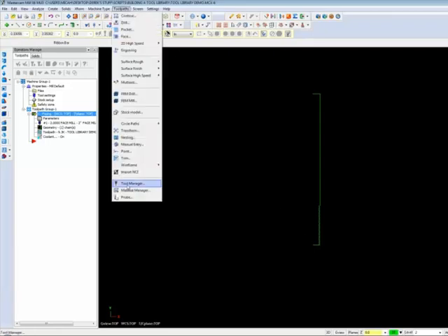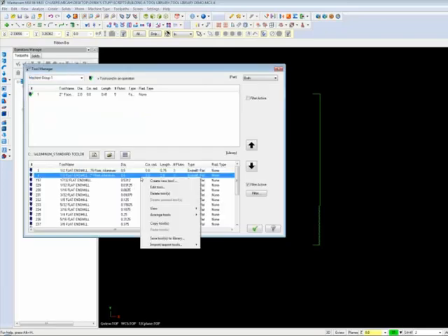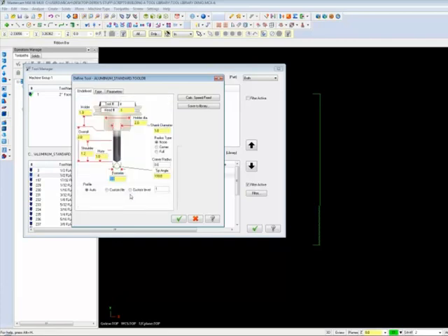Reopen the Tool Manager, right-click in the lower field, and select Create New Tool. The first thing to do is select the tool type. Since Mastercam doesn't have a thread mill definition, this tool will fall into the undefined category. Next, we'll need to enter the tool parameters. Since this tool will not be part of the permanent tools, we'll make the tool number 0. This will serve as a reminder to assign this tool a number above 20.